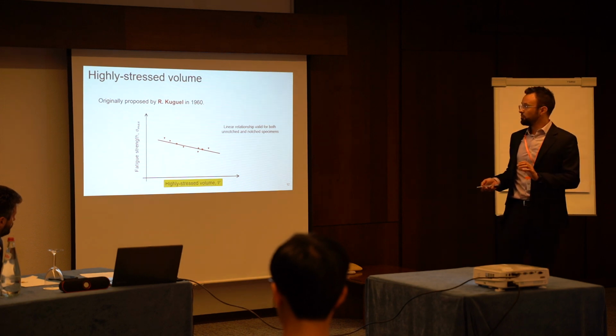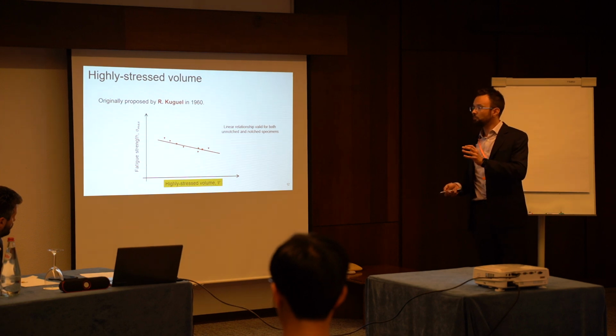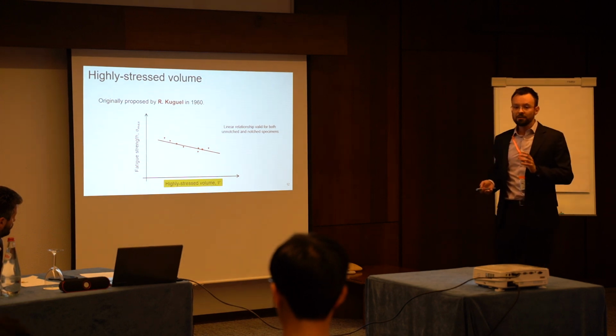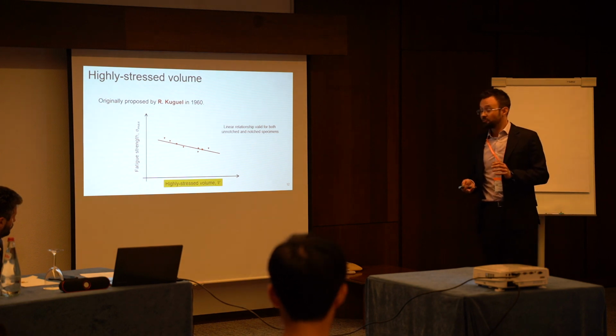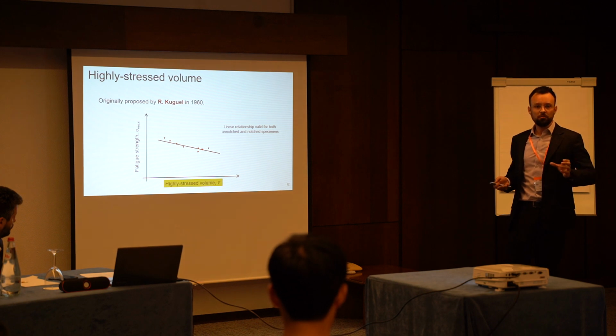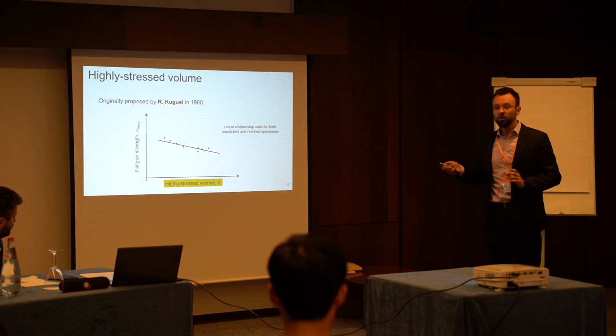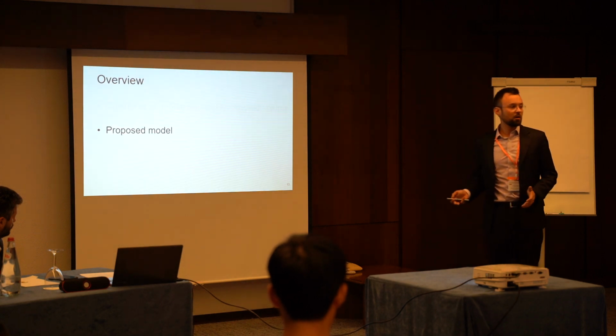So here we can find in the literature fatigue models based on this theory, but at least we didn't find any that combines the general Castillo model with this highly stressed volume theory. And this is our proposal.